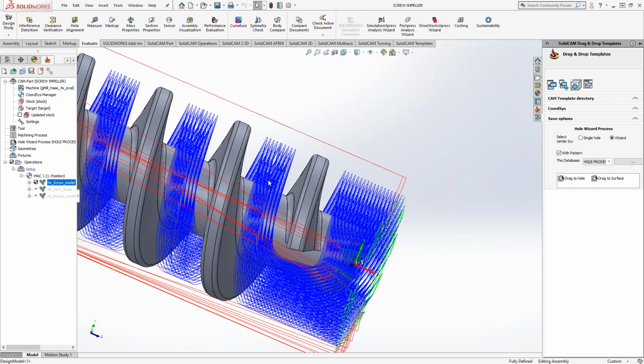Anytime there's a recognition function to a toolpath, I'm going to go towards that sometimes more than I go towards eye machining. Because a lot of times, especially with these screw machine manufacturers, cycle time is not their biggest thing. They have these massive parts where as long as the code is good, they've tested it out and simulated it, they let it run overnight. So cycle time is not the biggest deal with these guys. Eye machining, as great as it is, sometimes they need the accuracy of how they're going to finish the walls and all that. This is a really good toolpath. I like this one. In my mind, it is in competition to indexing a 3D eye machining.